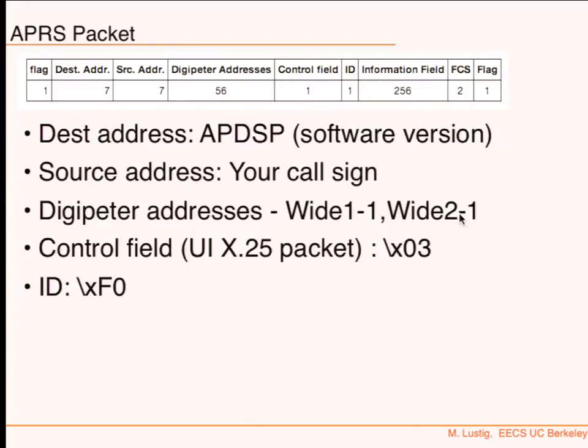Basically, it removes a number and then digipeats again. Okay, that's how it works. In the Bay Area, you probably don't want to do 2-1. You're just going to do 1-1 because it's enough. There are so many digipeaters here. If somebody picks you up and digipeats it, it most likely will get into an internet link. So just to reduce congestion, probably use just WIDE1-1.